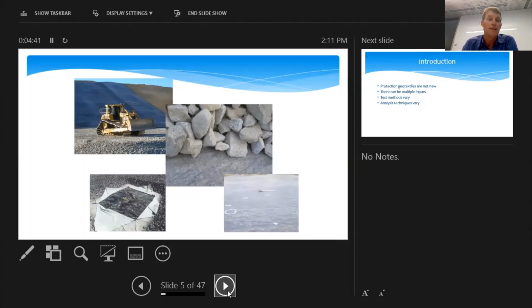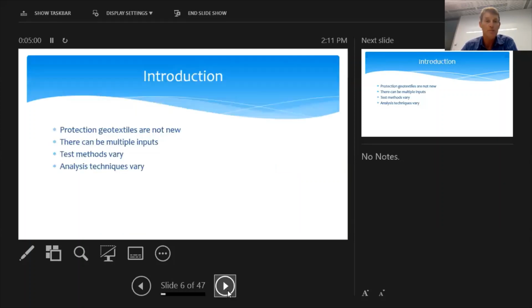In fact, the designs that we're dealing with are staying well away from puncturing, and we'll go into those details. And it's more about the indentations and the very limiting strains within the geomembrane. So once it's got to a point where there's punctures knocked through the geomembrane during installation of the drainage gravel, you're in real trouble.